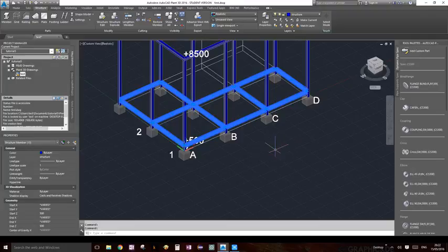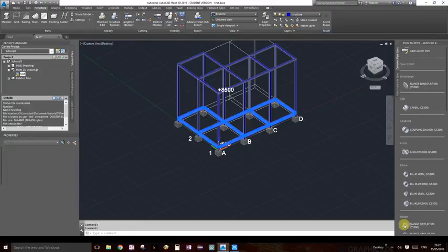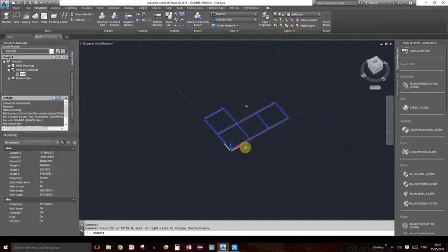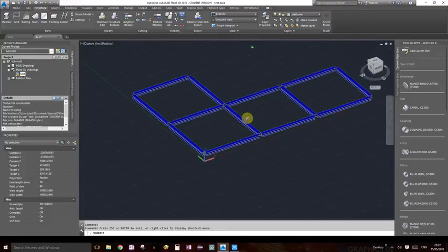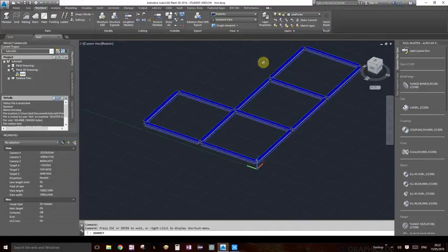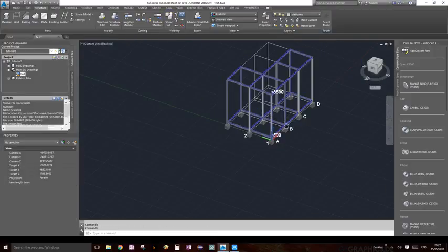Okay, so there you go, and now we have selected the entire bottom structure, and we're gonna go ahead and press this button from structure visibility, this tiny little button there called hide others, and voila, everything is hidden. But it's still there. You can still draw everything and it'll still show up, just not everything else. So there's not a lot of interruptions and viewing clashes and whatnot. And once you've hidden everything, you can easily click on show all, and it will pop it back in.